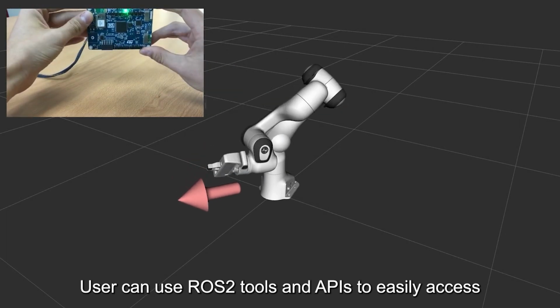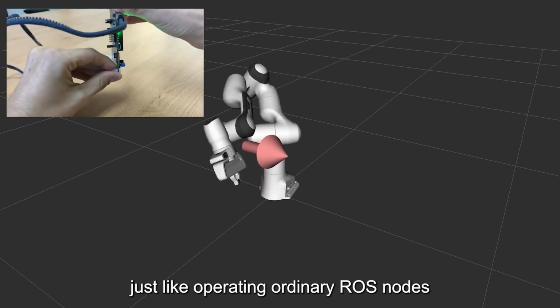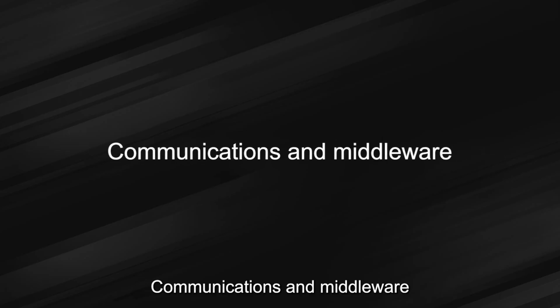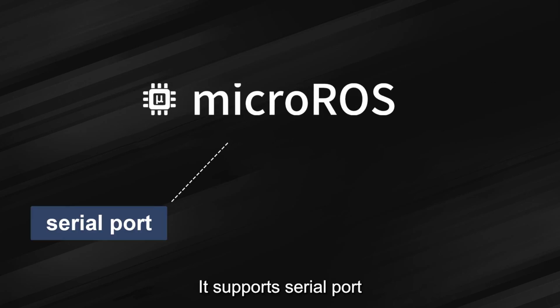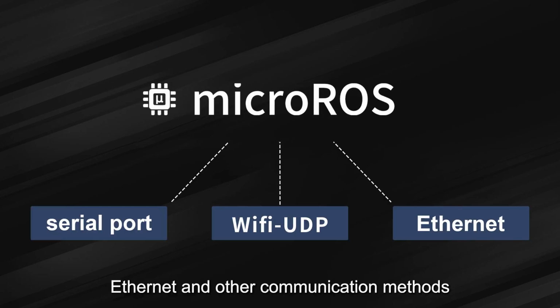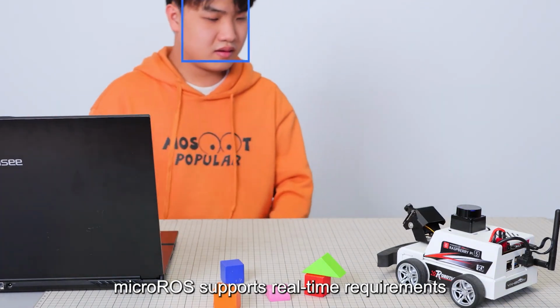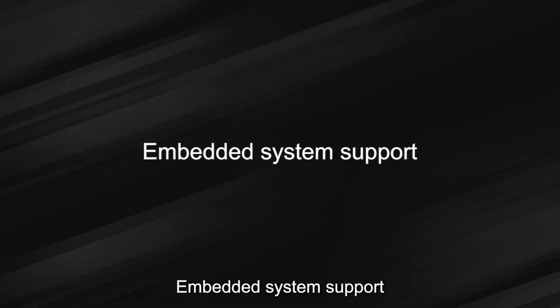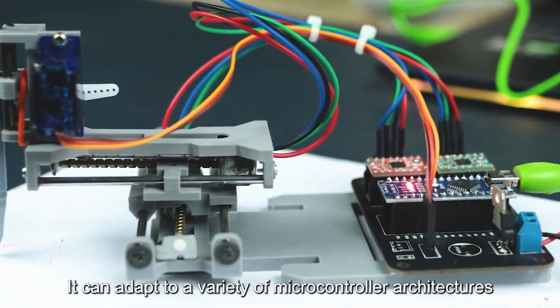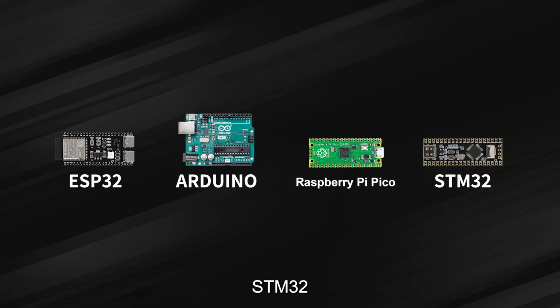Users can use ROS 2 tools and APIs to easily access and manage MicroROS nodes, just like operating ordinary ROS nodes. Communications and middleware. MicroROS can communicate with other ROS 2 systems. It supports serial port, Wi-Fi UDP, Ethernet, and other communication methods. Real-time performance. MicroROS supports real-time requirements and ensures system reliability and response speed. Embedded system support. It can adapt to a variety of microcontroller architectures, such as ESP32, Arduino, Raspberry Pi Pico, STM32, etc.